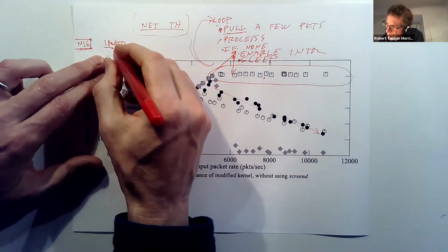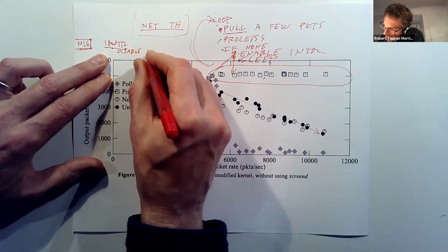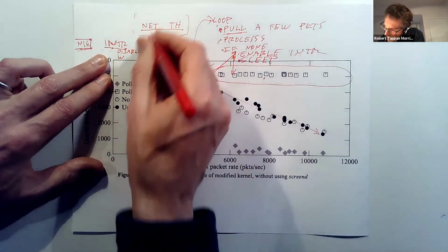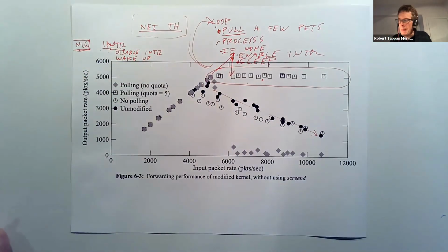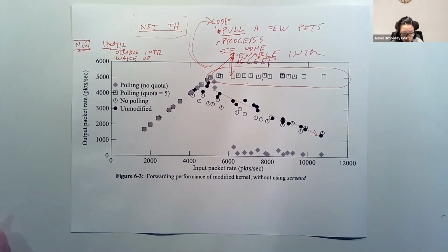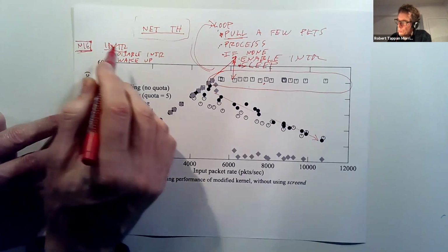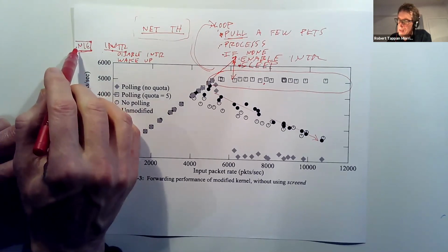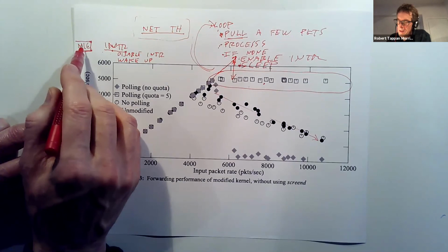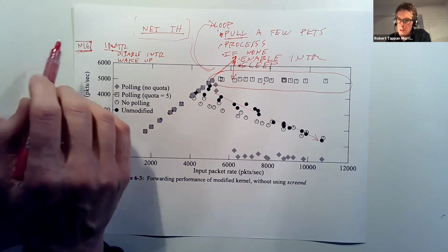Yeah, so what happens in the interrupt handler is it disables interrupts on this NIC and then wakes up the network thread. And that's all it does, and it returns. I guess my question is, when the interrupts are disabled, can the NIC still put packets on its own buffer? Yes, the NIC is self-contained. So it has internal buffering, regardless of whether interrupts are enabled or disabled. All that happens when a packet arrives is that the NIC appends the packet to its queue of packets in its own internal memory. That's all that ever happens when a packet arrives.